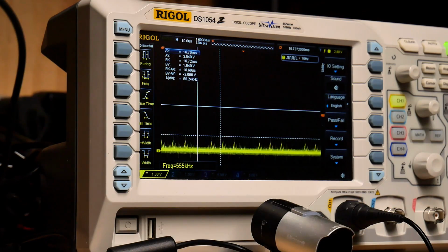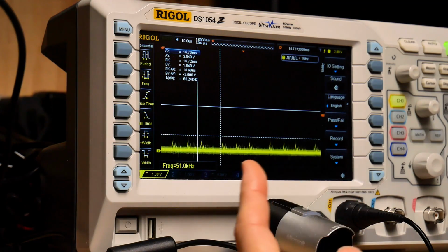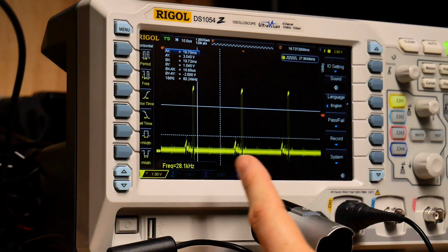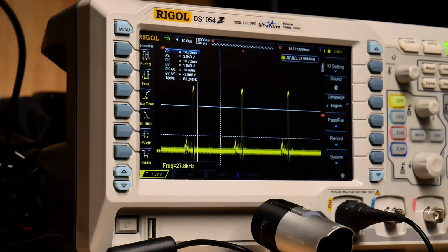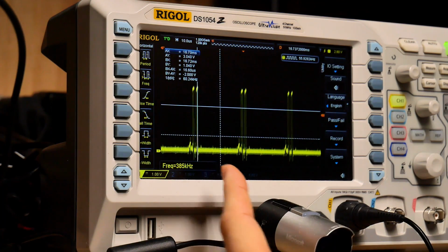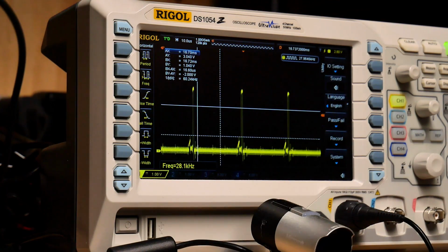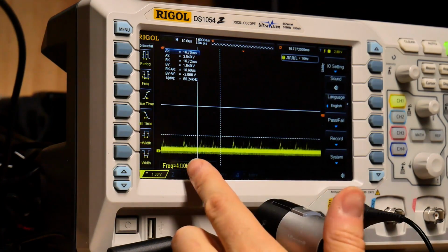Now on the next chip, this is one of the ones that's just held low. This does not seem right. I am not expecting to see that on the bus. This looks normal. That's data line 1. Data line 2 looks absolutely normal. 3, that looks normal as well. 4, that's fine. 5, this looks really screwed up.